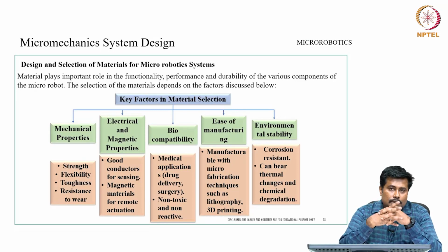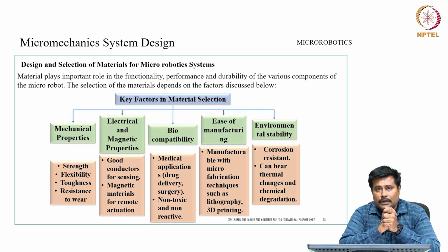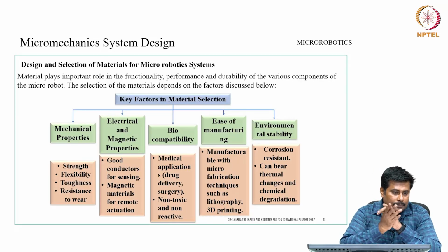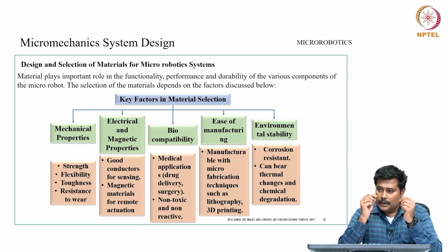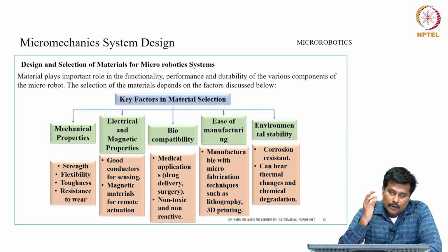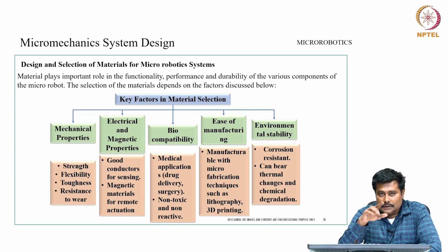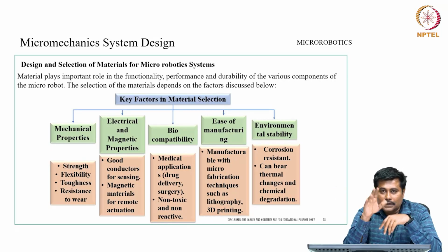If you observe this negative Poisson ratio, it is getting generated not only because of the material, but it also depends upon the structure. In the case of an auxetic structure, the structure is in the form of a pentagon. When we apply a load, there is an elongation.